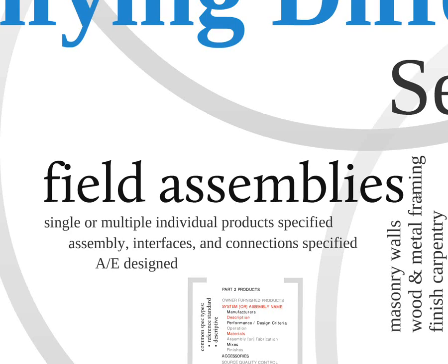That's a very important distinction, Dave, that I want to follow up on a little bit, that these field assemblies, and you'll see this when we get over to specific examples, in this case, the performance of the building element, exterior wall or whatever, is the responsibility of the design team. They're the ones who pick products from multiple manufacturers that have to go together, have to be compatible, and have to work together to provide the desired performance and characteristics for that building element.